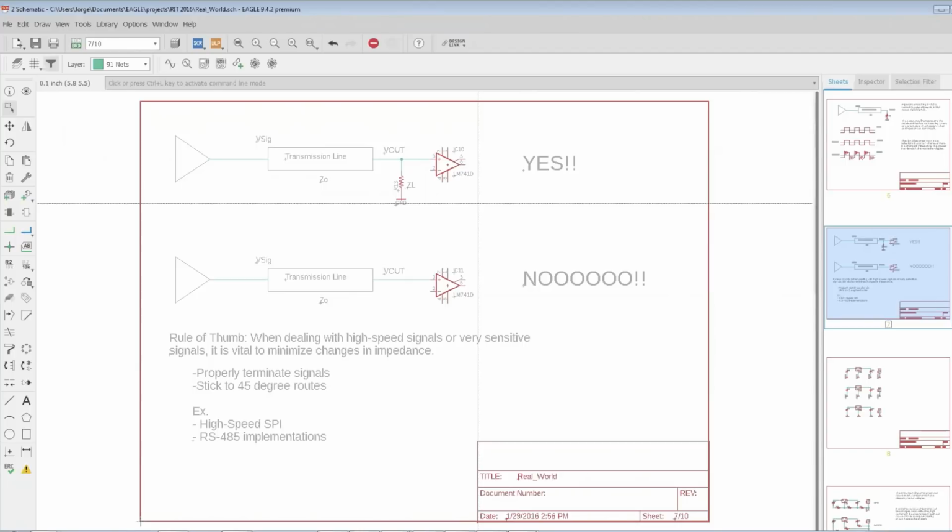Okay, and the reason is you're going to have that impedance mismatch, and you're going to get a ton of distortion on the signal. So by using, and this is one way to terminate, there are many ways to do termination, depending on the situation, but this is possibly the simplest one, to put in that load resistor there in parallel, because a high impedance in parallel with a lower one, the effective impedance is going to be basically the lower one, and that will help minimize distortions. So keep that in mind, okay?